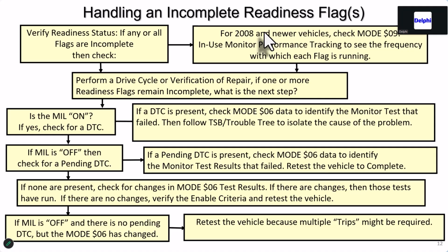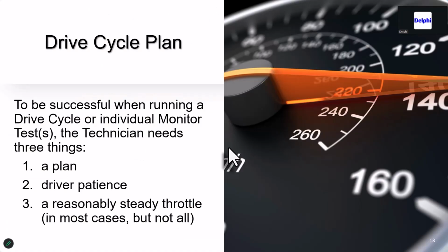to your advantage. The other things we'll be addressing in this will be things like that classes will be mode 6, and we're going to talk about averaging, where you could be in an averaging mode and you're not done, and you're going to have to maybe run this thing 3 or 4 more trips to get it to establish a pass-fail value. So keep that in mind. This is a little chart that's on my website too, and we're going to break this down over the 3 sessions. Okay, drive cycle plan.